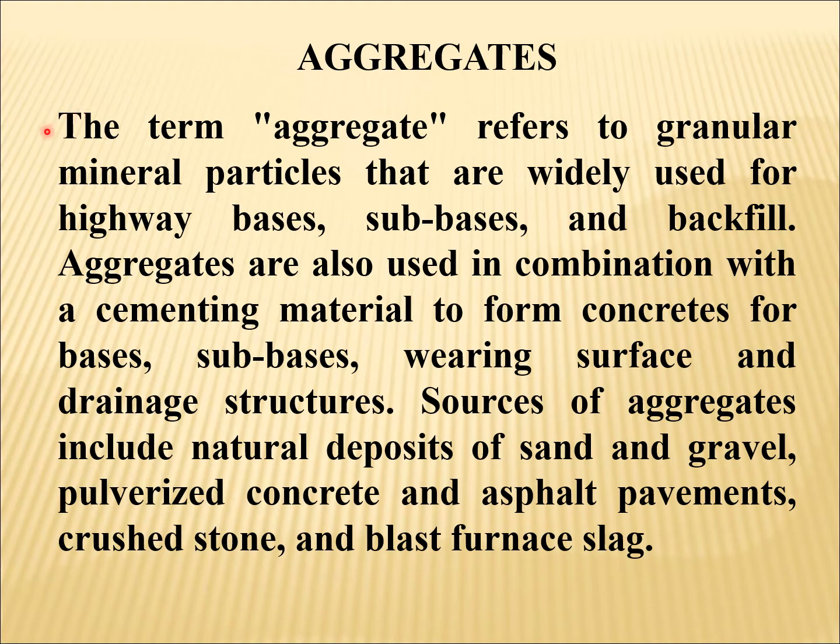Aggregates. The term aggregate refers to granular mineral particles that are widely used for highway bases, subbases, and backfill. Aggregates are also used in combination with the cementing material to form concretes for bases, subbases, wearing surface, and drainage structures. Sources of aggregates include natural deposits of sand and gravel, pulverized concrete and asphalt pavements, crushed stone, and blast furnace slag.